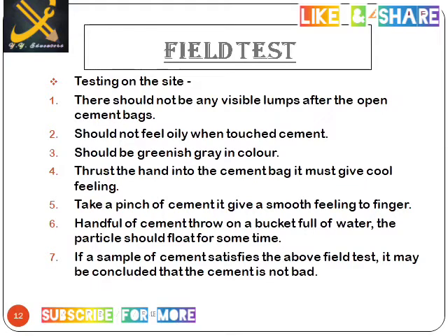Field test, the testing of cement on the site. There should not be any visible lumps after opening the cement bag. It should not feel oily when you touch the cement. Cement should be greenish gray in color. If we thrust a hand into the cement bag, it must give a cool feeling to our hand. Take a pinch of cement, it gives a smooth feeling to the finger. If a handful of cement is thrown into a bucket full of water, the particles should float for some time.